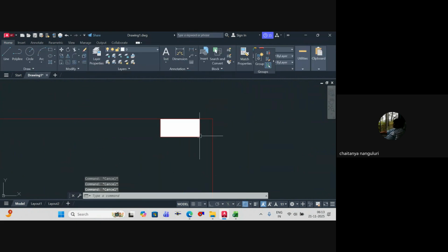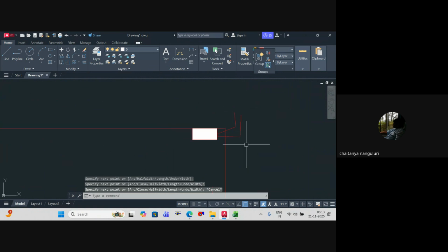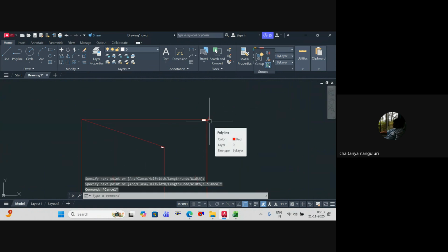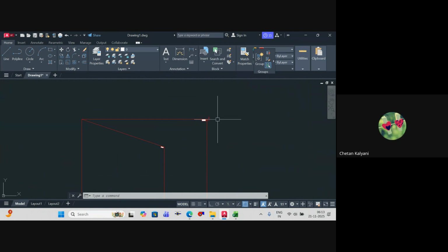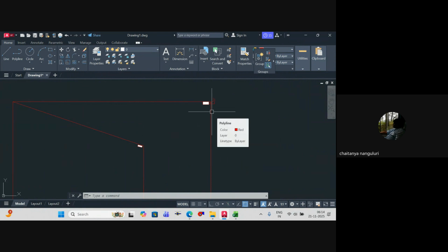This is your cables. So again, in this also you have two types. One is your NO type and the other is NC type. Generally, NC type means whenever the magnet is there, it will be in closed state. NO means whenever the magnet is there, it will be in open state. It will be reversed once the magnet touches it. This is a simple magnet, nothing else. So when the door is closed, don't you think both will touch each other if we install it properly?